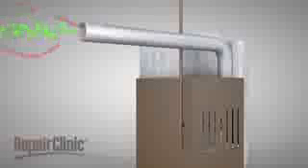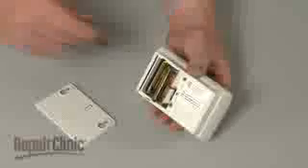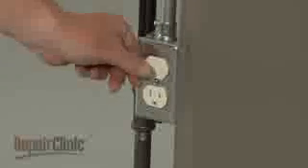Under normal working conditions, the furnace will exhaust the carbon monoxide through a flue or exhaust pipe to the outside of the home. If the flue or pipe breaks, cracks, or rusts, carbon monoxide will contaminate the air. To help keep you safe, a carbon monoxide detector should be installed near the bedrooms of your home, and its batteries checked regularly. If a leak is detected, the furnace should be shut off immediately.